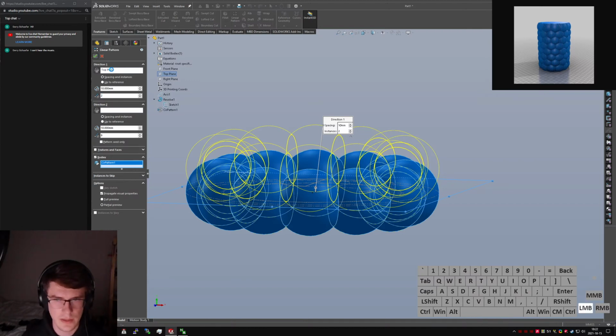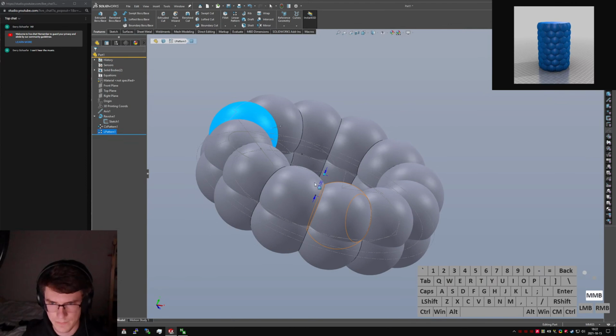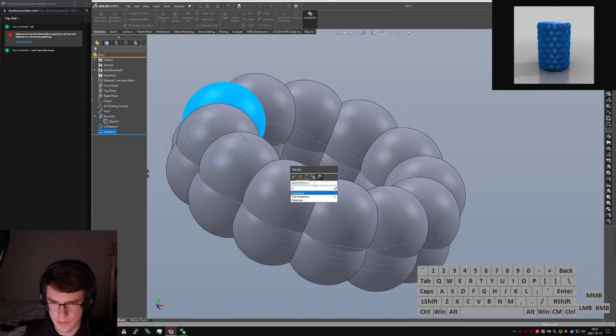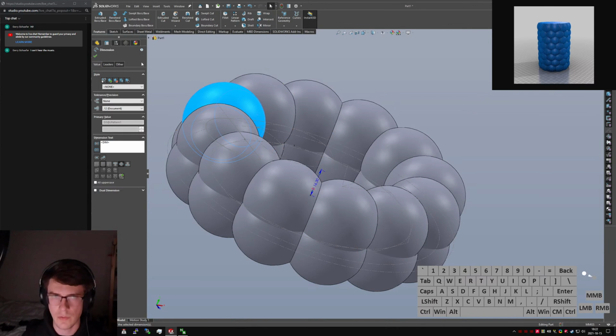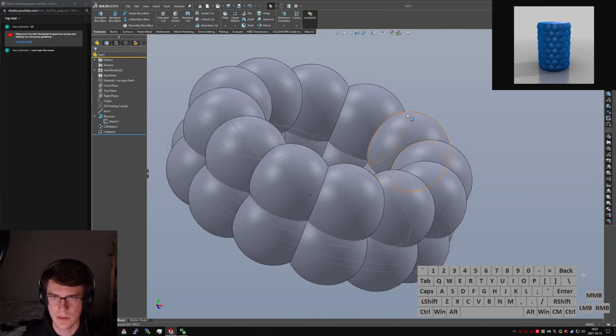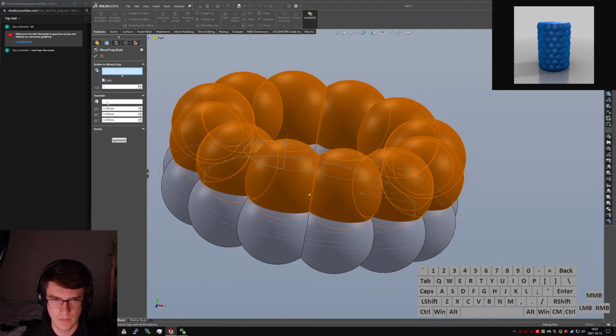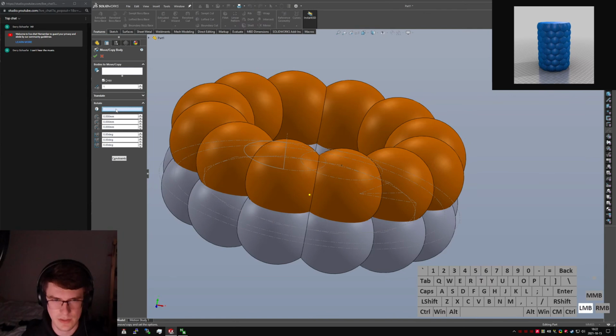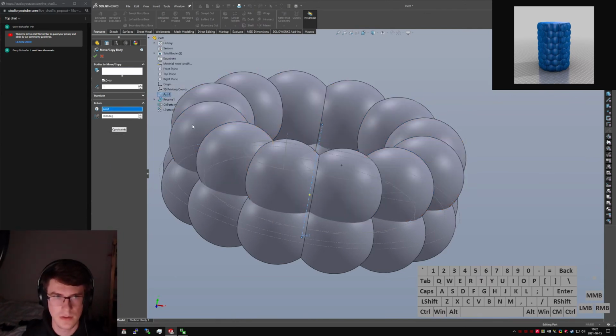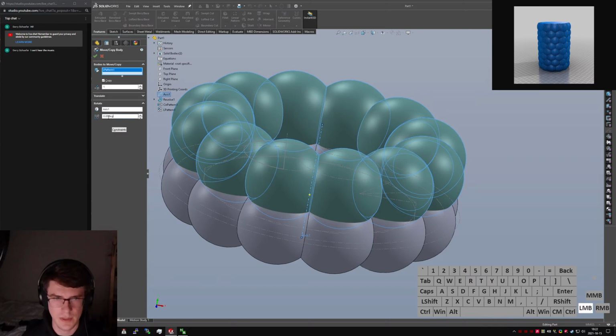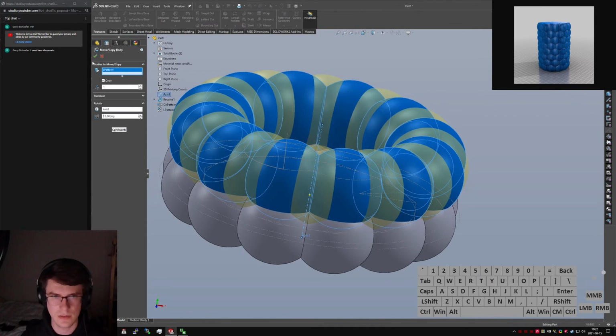And we're going to leave that for now, that 10 millimeters. So we can come in here and say equals height at sketch 1. Ooh, that won't quite work. I don't think that'll quite work. I mean, still worth taking a peek at just to see, but... move this body and rotate 360 divided by 24, because we need... Actually, don't copy, just rotate.